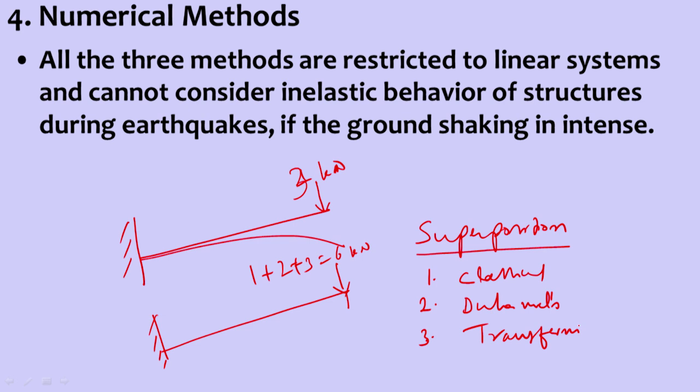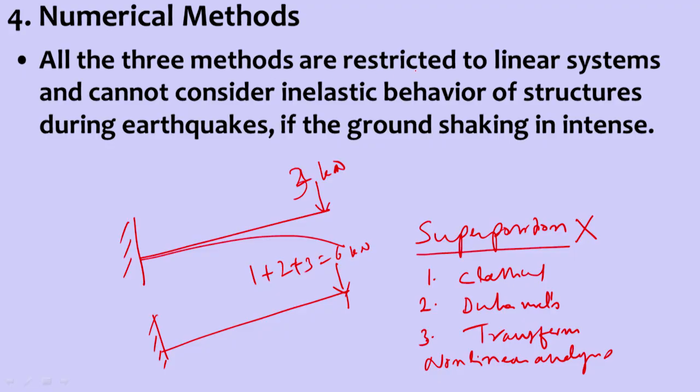When it comes to nonlinear analysis, the superposition principle cannot be applied. So, we need a more powerful technique for solving dynamic equilibrium equations, and for that we rely on numerical methods. All three other methods are restricted to linear systems and cannot consider the inelastic behavior of structures during earthquakes.